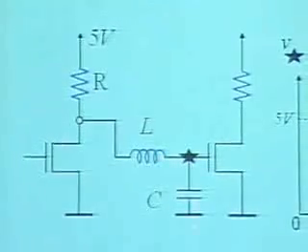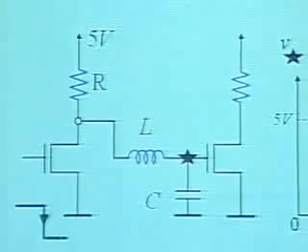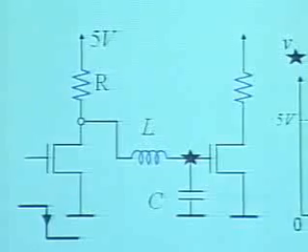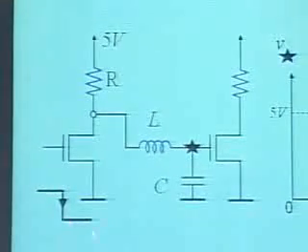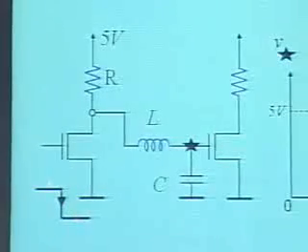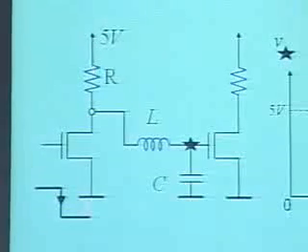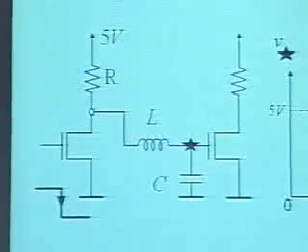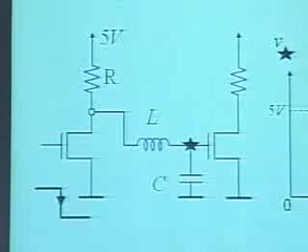If you look at the circuit, that circuit formed an RLC pattern. We said, let's drive this with a 1 to 0 transition at the input. The 1 to 0 transition at the input would cause this transistor to switch off, and this node would then go from a very low value to a high value.